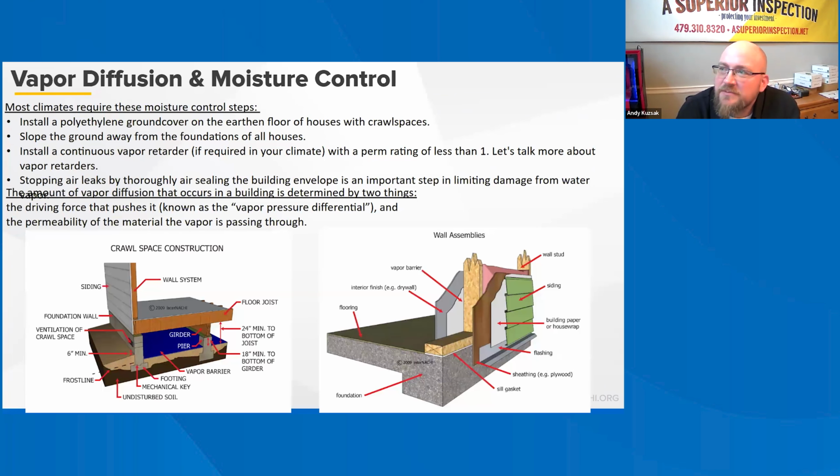Even without air leaks, small amounts of moisture in the form of water vapor can pass directly through a building's envelope through a process called diffusion. Vapor diffusion from a damp or wet basement into the living space can significantly increase the moisture levels inside a home. Most materials, even glass, are unable to completely stop vapor diffusion. Thus, calling something a vapor barrier is a bit of a wrong label. The current trend in building science is to refer to materials as vapor retarders, meaning that while they retard or slow down the movement of water vapor, they do not completely halt the process.